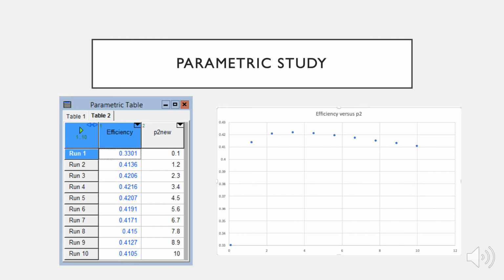Something we could have done to make our total capital cost smaller would have been to buy the refurbished turbines instead of the new ones. But we decided on buying the new turbines because they had a higher isentropic efficiency of 87% as opposed to 80%.